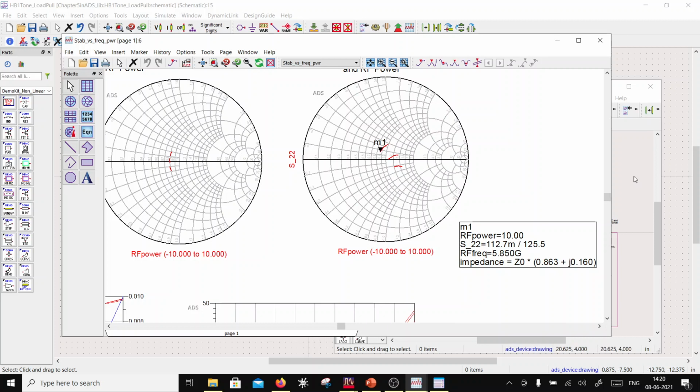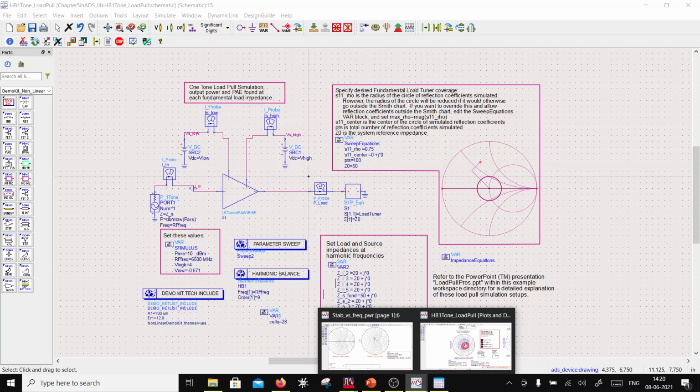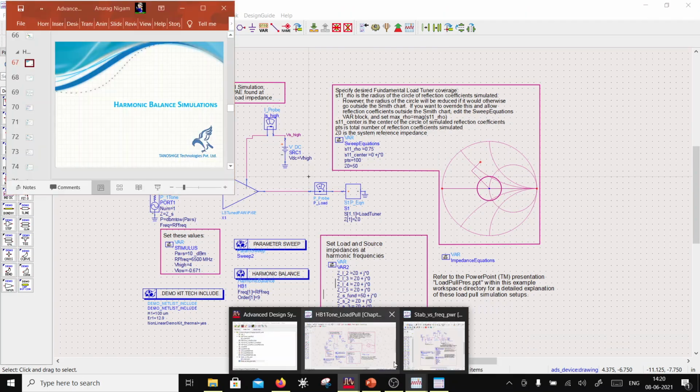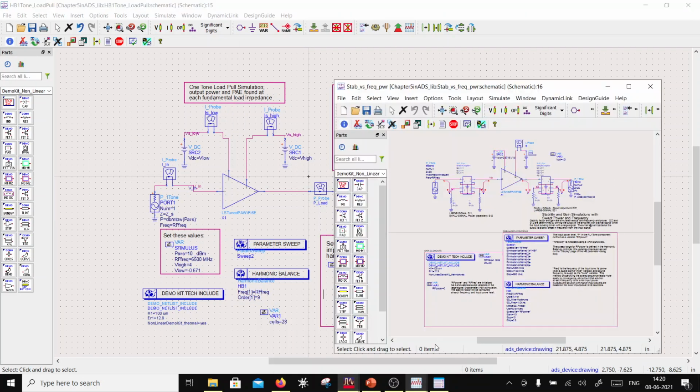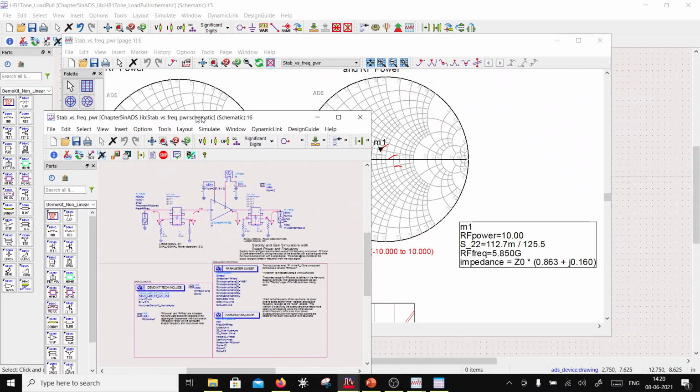Here in load pull, you were blindly crunching your numbers, right? And you arrived at the same results by brute force, versus you were intelligently matching your impedances under compression over here, and you will get the contours on the 50 ohm, right? There's no question of load pull giving me the impedance where I should be tuning. So blind and brute force versus intelligent.